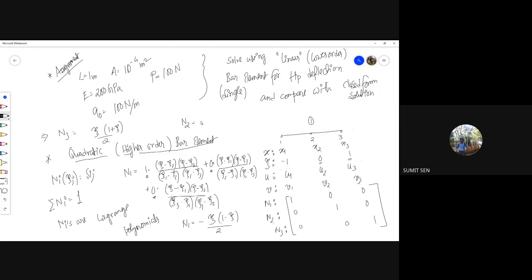It should be 0 at minus xi, so 1 plus xi. Sorry, it should be 0 when xi equals minus 1. It should be 0 when xi equals plus 1. Okay. Now let's see what expression it gives me. 1 minus xi squared. Okay. And actually, I don't need to do any kind of modification because at xi equals 0, this essentially becomes 1. Okay.